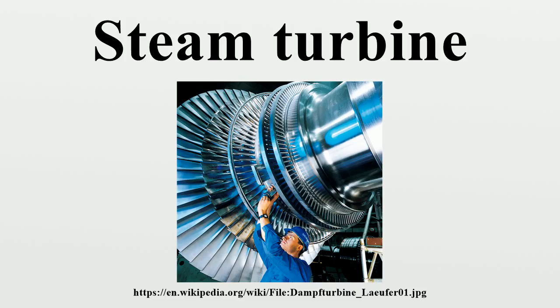Two-flow rotors. The moving steam imparts both a tangential and axial thrust on the turbine shaft, but the axial thrust in a simple turbine is unopposed. To maintain the correct rotor position and balancing, this force must be counteracted by an opposing force. Thrust bearings can be used for the shaft bearings. The rotor can use dummy pistons. It can be double-flowed. The steam enters in the middle of the shaft and exits at both ends, or a combination of any of these.